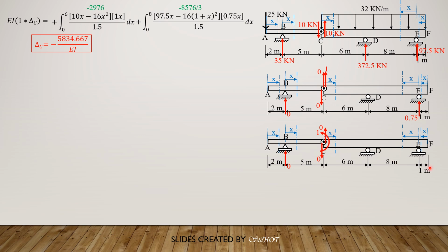Then if we sum up moment about D, the reaction at E should be downward. So the downward reaction times 8 equals 1. That means this is 1 over 8 downward. So same sectioning. Then we'll begin with the third section CD, because the first two would be 0.